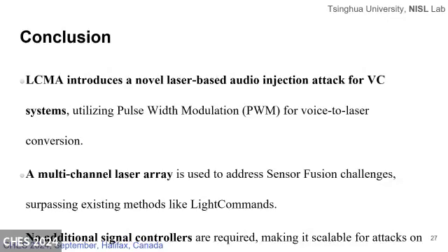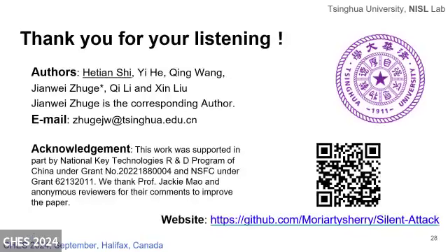Our work presents a new approach to laser-based audio injection attacks on voice control systems, using PWM modulation to convert voice commands into laser signals. Our multi-channel laser arrays effectively tackle the sensor fusion challenges, improving on methods like Light Commands. Since no additional signal controller is needed, the system is easy to scale to target multiple microphones in the area. So here comes the end.